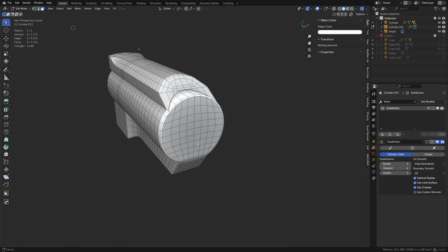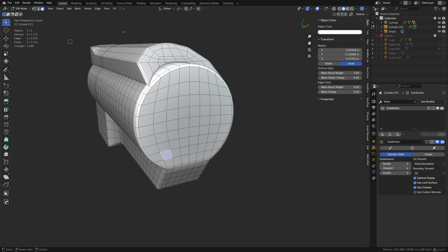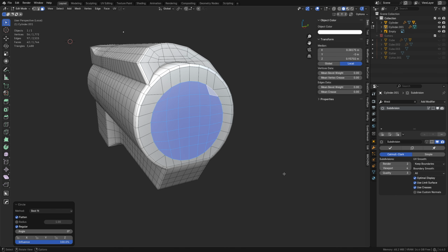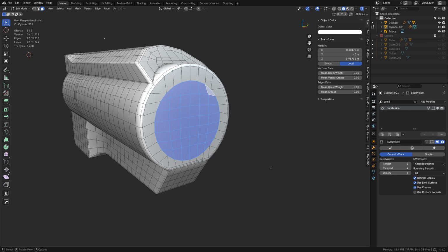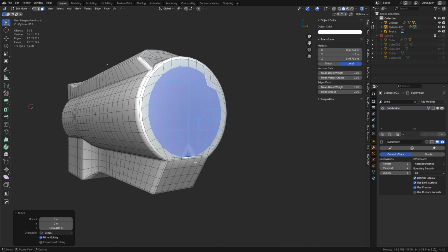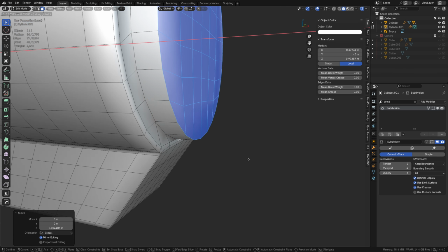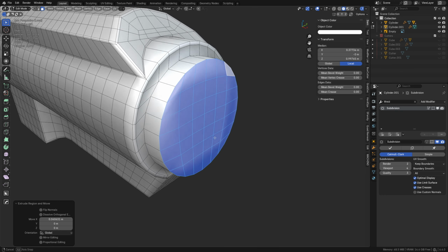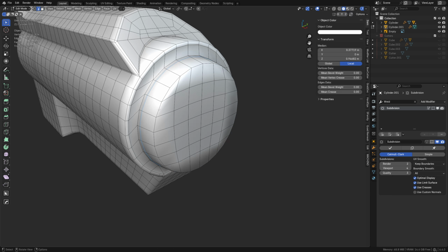Oftentimes you can use a mesh like this that you've worked out to create additional details as well. So for example, if we needed a hole in here, we can use loop tools and do circle, something like that, right? So now we're at that point where we can start using our mesh to create the other needed geometry. And if something is misaligned, you work it out: push and pull those vertices around, cut them up, remove them, duplicate them, separate them, whatever you've got to do to get it to work out. These become a lot easier to manage or deal with.